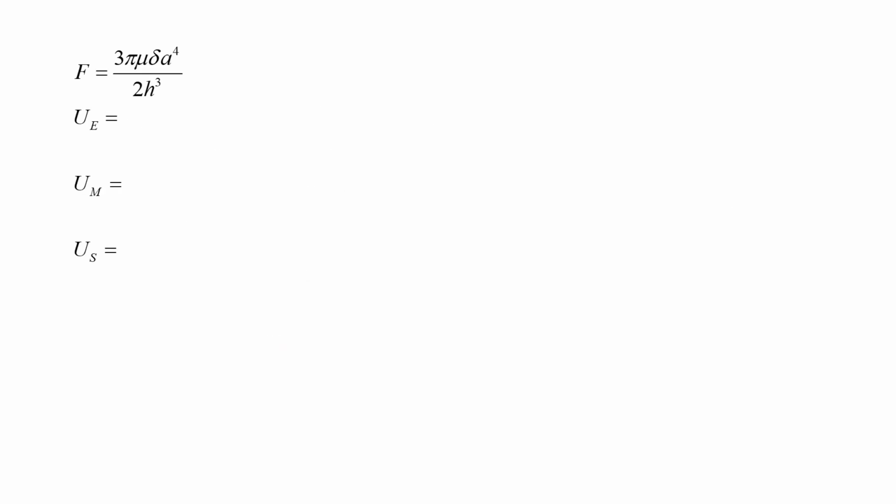So, now let us estimate what is the pull-off load that will be required to separate this top plate from the surface when there is adhesion between them. So, when there is adhesion between them, the surface energy is minus W A into the area. So, area is pi a square, remember that. So, pi a square is the area of contact.